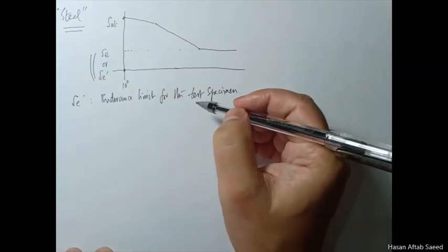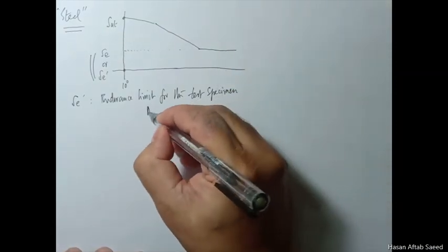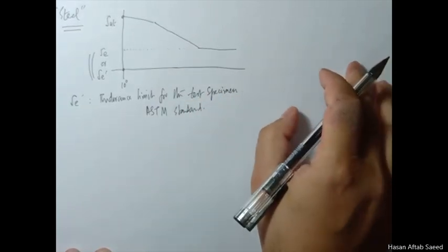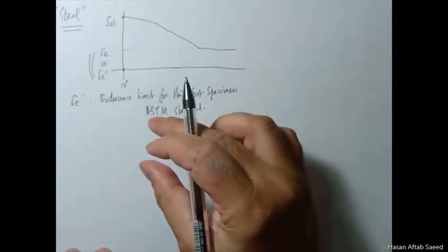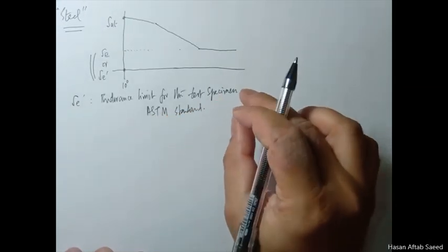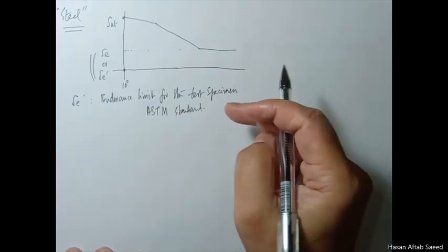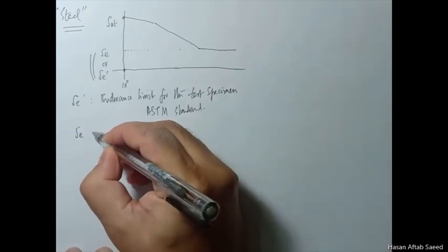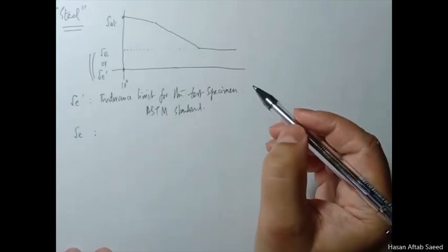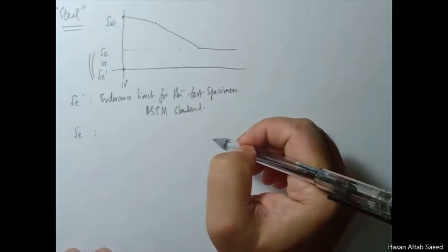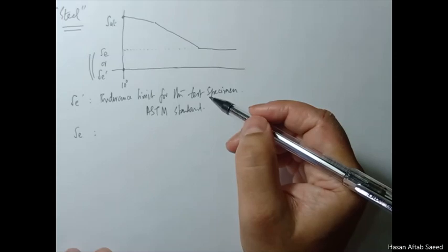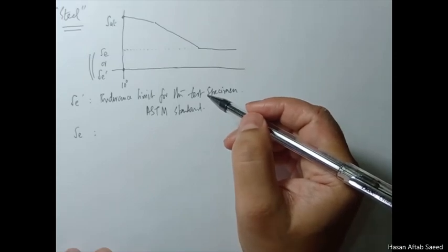You know that the test has a number of specifications, ASTM standards. It has to be polished. It has a certain dimension, a certain kind of completely reverse loading, and so on. There is a lot of detail. But in real life, your components, even of the same material, will not be conforming to all those requirements that you can make sure are applied in the laboratory. You cannot ensure that, and obviously the sizes and shapes will be different depending upon the functionality of the part.